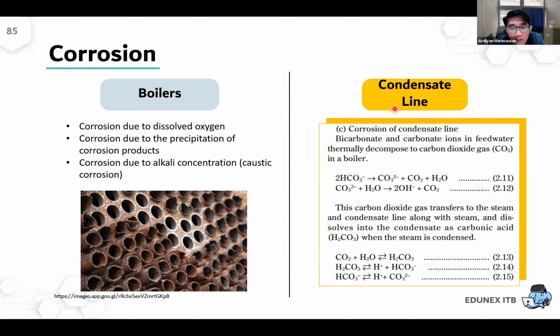But if you decrease the pH, the possibility of hardness is lower, but the possibility of corrosion is higher. And then for corrosion, you can add what we call corrosion inhibitor. They will form a certain film on the surface of the tube or on the surface of the boiler proper, so to reduce the possibility of the corrosion.